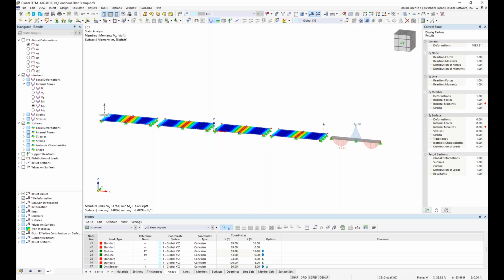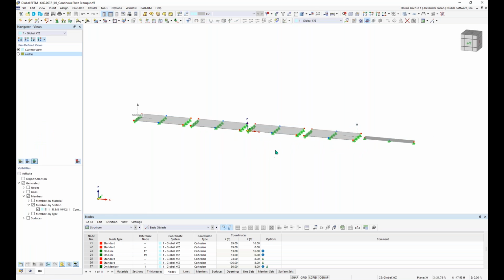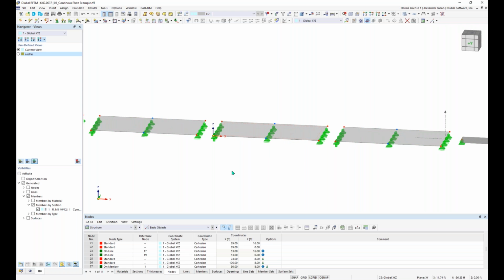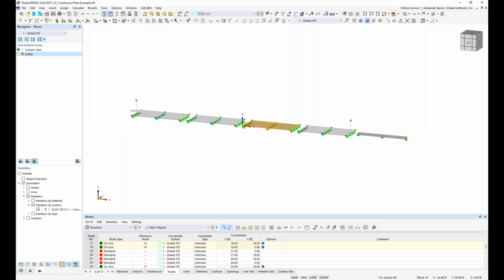One other thing I wanted to mention before we move on is highlighting. If you drag from left to right, anything within the box, that's engulfed in the box, will be selected. And then if you drag from right to left, anything touching the box will be selected. So that is how highlighting works.